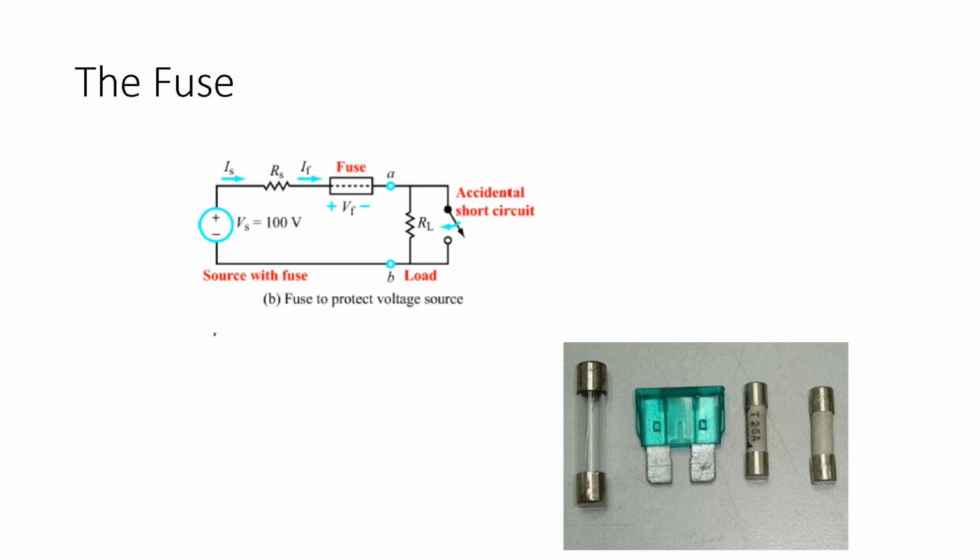Fuses are used in houses too, and circuit breakers and trips. The older style is fuses, and they're essentially little tiny metal wires in a little container that when you plug them in and too much current goes through at once, they heat up and then they break. And that protects your house from essentially having the wires heat up so much that they catch fire in the walls and your electronics in between catch fire, and that's to prevent fires essentially.